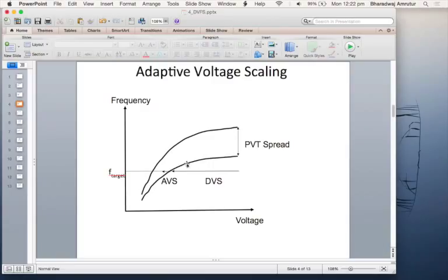So you can use this table or this curve or this mapping, which is at the lower bound of the F to V spread, and you say I'm going to use that as my table or mapping. So how do you find that table? How do you find this curve F to V? I'm using the word table because this curve F to V is easily stored as a table, where you just take a few frequency points. You don't need that much. You have max frequency, maybe 3/4, a few discrete points down to half, maybe 5 points or something. That means you're taking 5 such points along this curve and corresponding 5 voltage points. That could be an F to V table, which is stored somewhere.